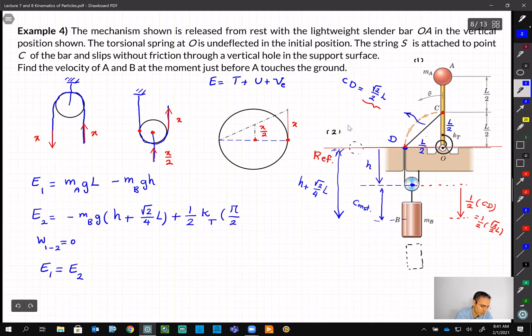In this course, always radians squared. If by mistake you put 90 here, you can imagine it's going to be a very, very large number, and your whole solution is wrong. The formula was developed so that we want radians here. So if we rotate 90 degrees, this is the amount of energy that is saved in this spring. So this is our potential energy.